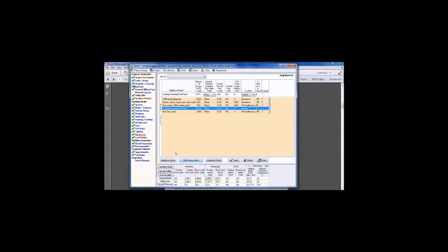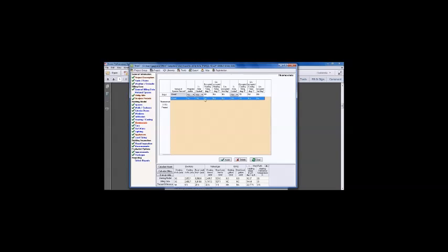My model is also 30% over predicting my heating end use. So after I balance out my internal gains and my baseload stuff, I'm going to focus on things like, is my thermostat setting reasonable? That might be too high, but the homeowner told me that she keeps it at 68 pretty much all the time. That might come down a little bit, but it's probably not going to address it. The whole point of the billing analysis procedure and the calibration is really for you to double check your assumptions.